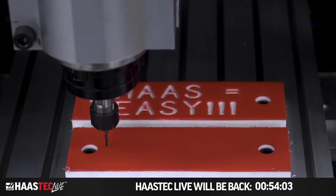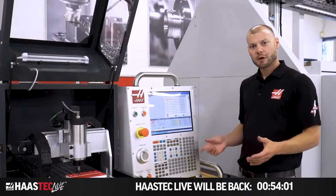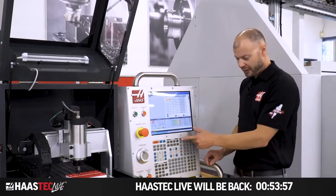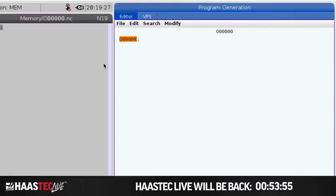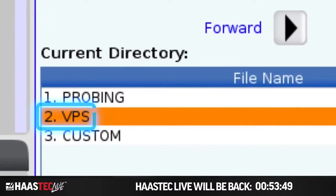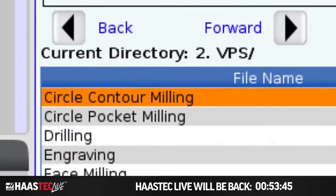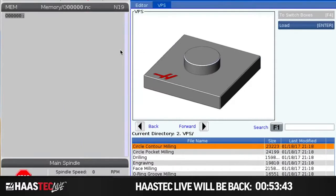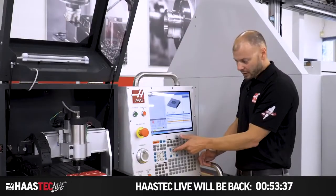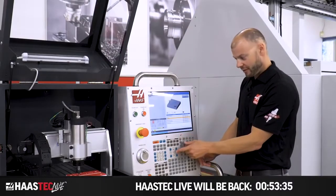Now that I have my X, Y, and Z established, let's go to VPS and make a short program. You can find VPS under the Edit button, then tab up to the top and over to VPS. As you can see here, you have a few different shapes we can easily make, like bosses, pockets, drill patterns, but today I think we'll do a little engraving.